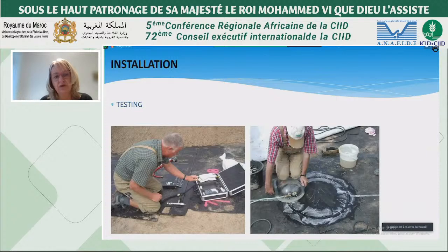Further to this, the test seams can be tested in peel and shear tests. You can also cut samples out of this liner system. As a good measure, it is good to take them from the end of such a seam and not to make a hole in the middle of it. And there are further testing procedures like ultrasonic testing, which can show that the weld is even over the whole length of the liner.